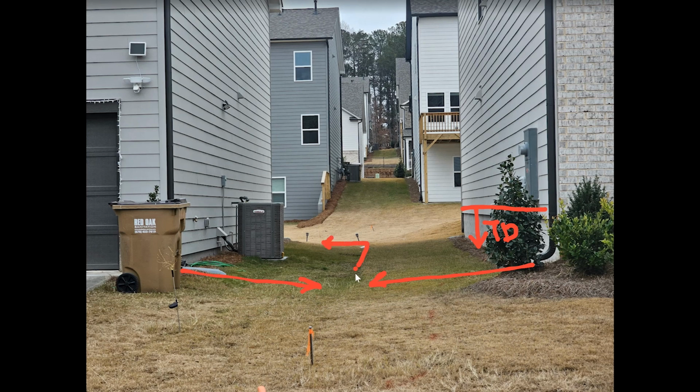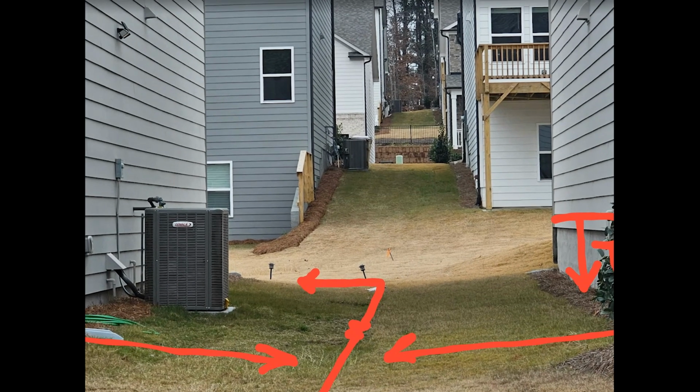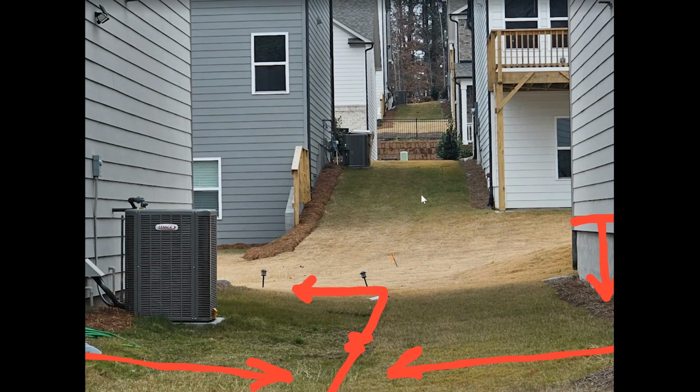And this does look like it's a midpoint where they're pushing the water to the rear of the house and then also to the front of the house. And again, it is at the property line. You can see the property line stake up front there and then also in the rear for these. And the houses were so tight together, you couldn't shift the swale close to the house. It needed to go down the property line.